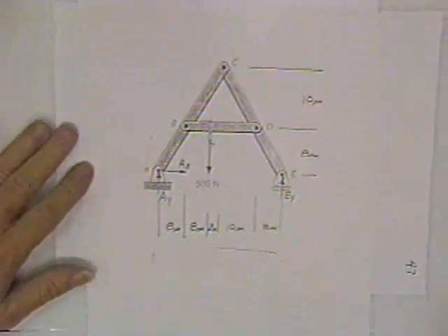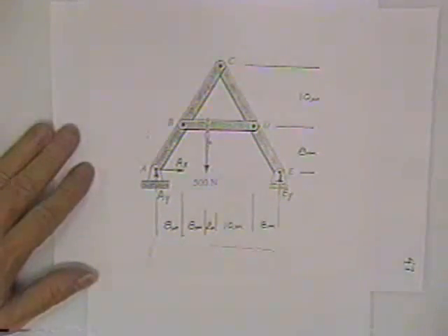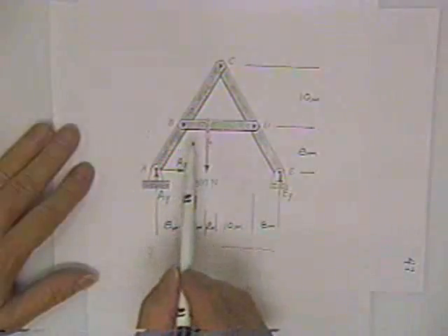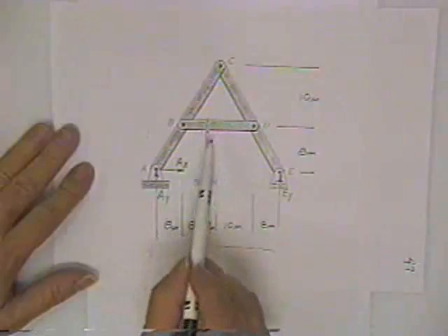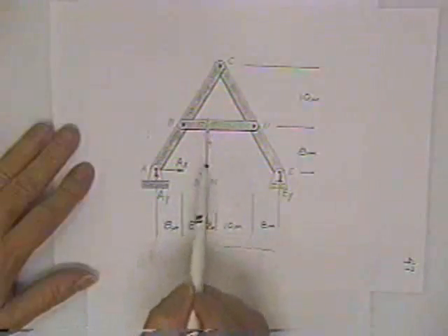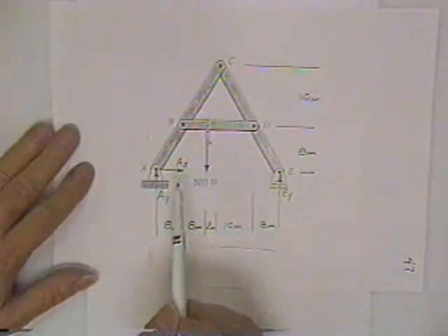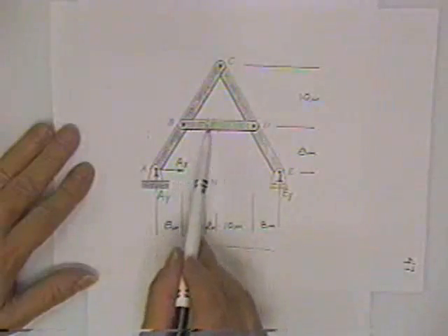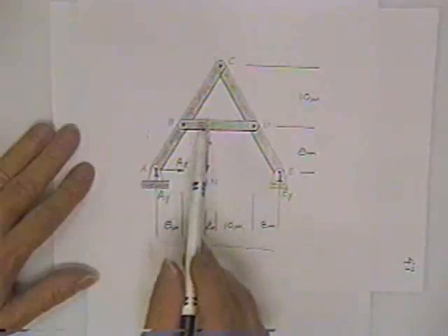The last thing we'll do are frames. Frames are pieces of steel. Unlike a truss, a truss never has a load in the middle of the member. It'd collapse immediately. The members are not strong enough in bending to resist that. So rather than being a nice slender piece of steel here, this is probably a 2x4 or something like that.